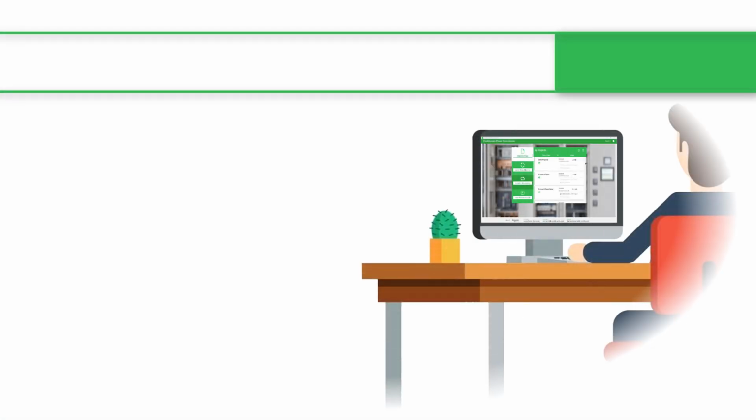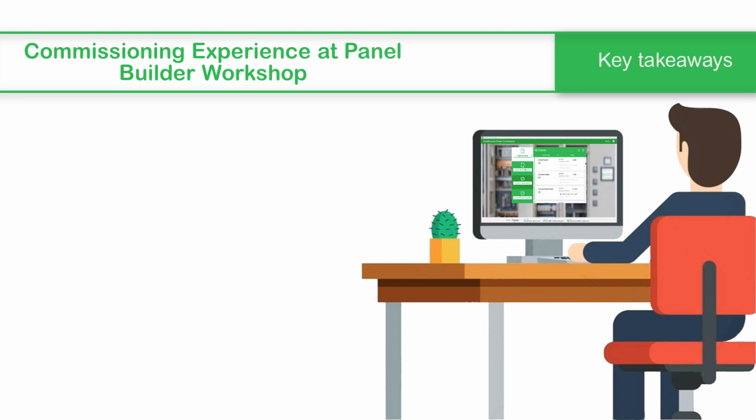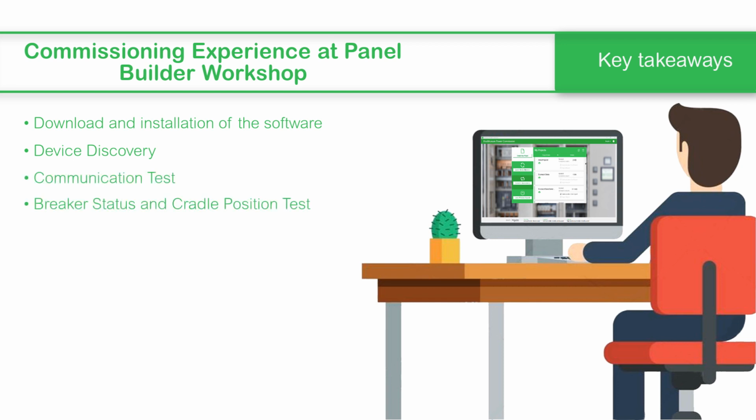This concludes the video on the EcoStruxure Power Commission experience at a panel builder workshop. In this demonstration, we saw how to perform the download and installation of the software, device discovery, communication test, and breaker status and cradle position test.